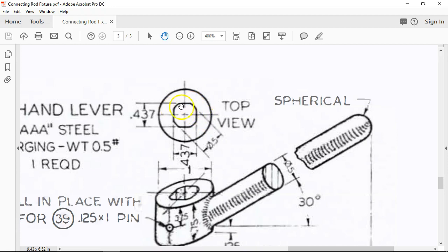We're going to have a round tool that goes in here, and either these are going to be really big radiuses or really small radiuses with a bunch of broken, very small tools. All right, so we put that angle in there. Then, yeah, the other option would be, okay, I'm going to wire EDM these. Well, not in a mass production environment. We're going to have a broach ground up so that I can push through there and have all that geometry pretty much generated from the, let's see, 4.5 inch. Yeah, we'd probably put the 7/16, 0.437 hole through and require the broach and steps to remove the rest of the material, make it accurate.